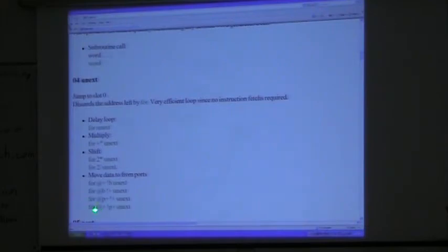Conversely, you might do a fetch from a port or from memory, and then a store P plus to the port from which you're executing this instruction word. We've got 4 instructions per word. Here we're using 3 of them in a loop. So that instruction is resident in the instruction word, does not need to be refetched. The only cost is the fetch and store of the data words.